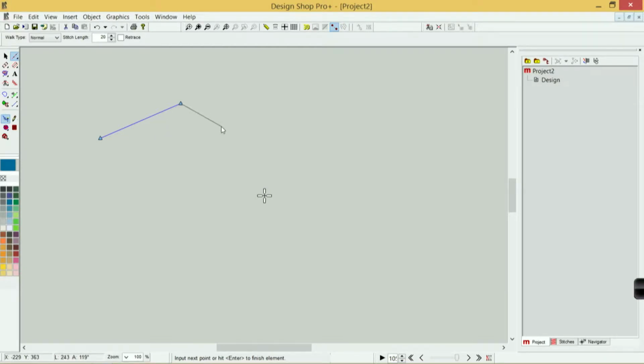And again, wherever I want to create this line, if I want to create a curve, I'll use a right click, which will create a circle along that line, and it will begin to curve out from that. And that curve will not be fully defined until I left click or right click on the other side of it. I try not to exceed 180 degrees in any set of 3 points. 1, 2, 3, and I try not to exceed 180 degrees in that.